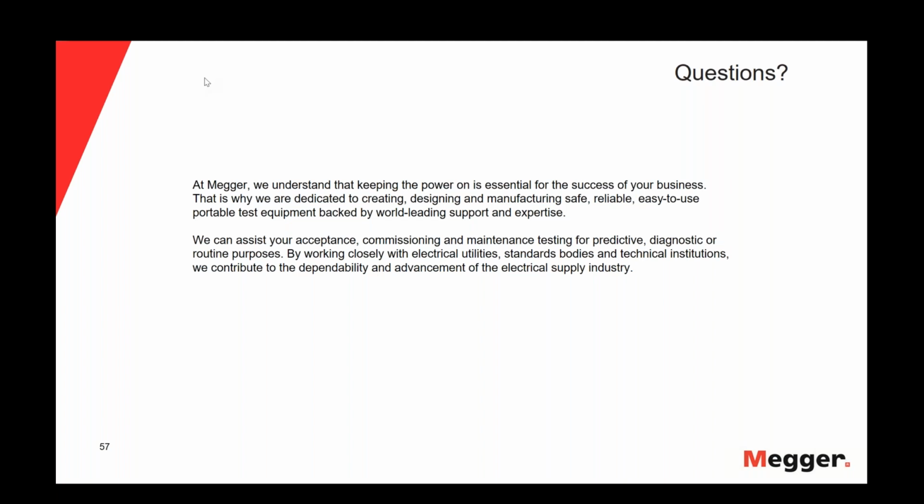Maybe there are two more comments on this. First of all, obviously it depends also on the diameter of the cable. Smaller diameter cables have smaller bending radii. The other thing, which is very different, is solid core cable compared to stranded core cable. Solid core cables are much more sensitive to bending radius than stranded conductors.